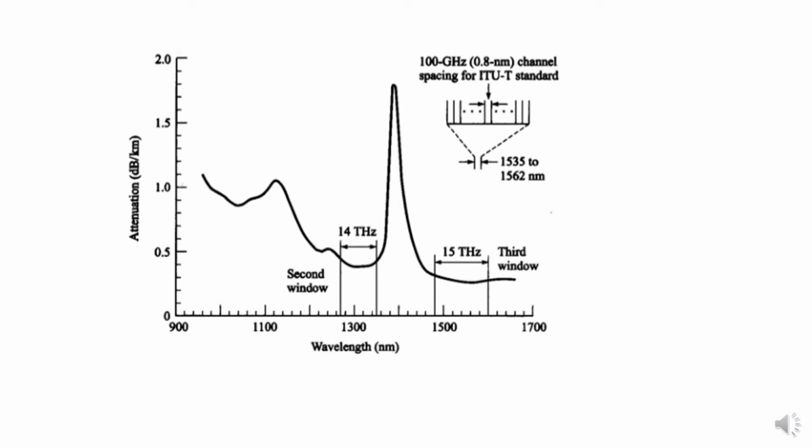The thing is, we are not utilizing this 30 terahertz for the communication or transmission of data. If you are using only one transmitter and one receiver, then the optical window is highly underutilized, and that is essentially where the origin of WDM lies. We are trying to exploit the maximum bandwidth which the optical fiber is offering us. The optical fiber has to make efficient use of the bandwidth. That's the motto behind the origin of WDM.